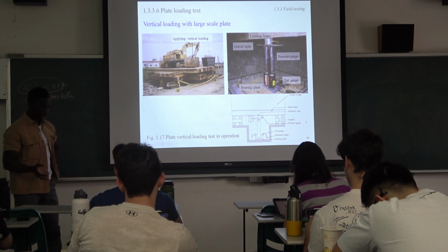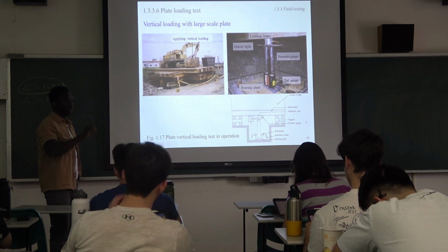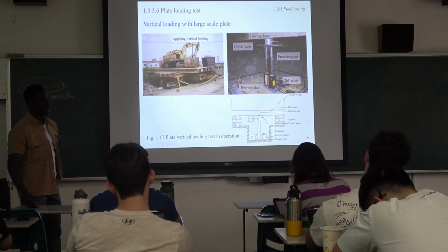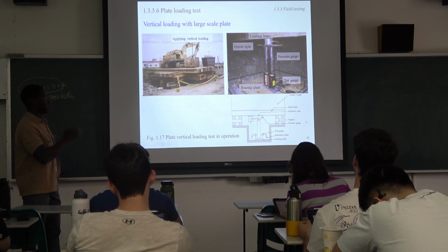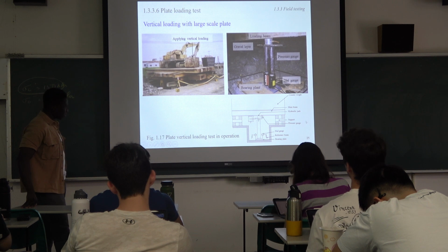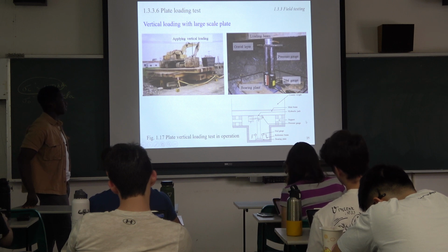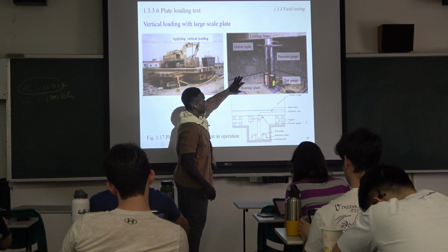If you remember, in the exercises, you have to use a lot of formulations and try to use the soil parameters or the soil conditions and whatever forces you are dealing with to determine the ultimate bearing capacity. But this is the field test. They can just directly use this type of condition to determine the ultimate bearing capacity of the foundation or the soil underneath. And you can see the hydraulic jack is already here.